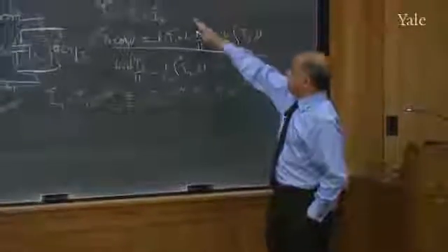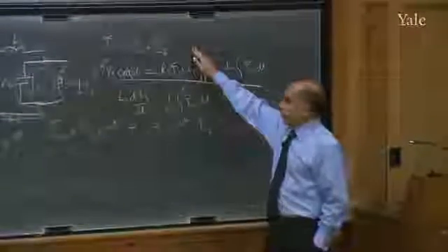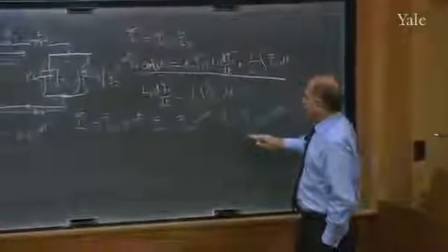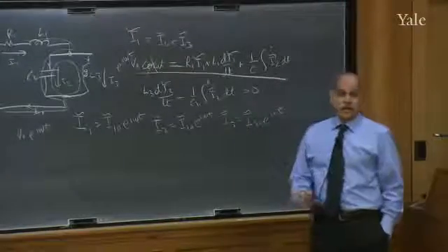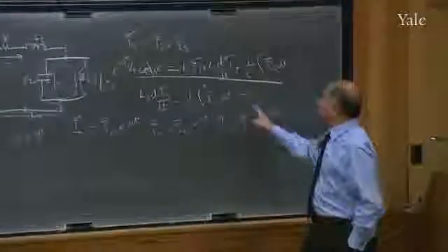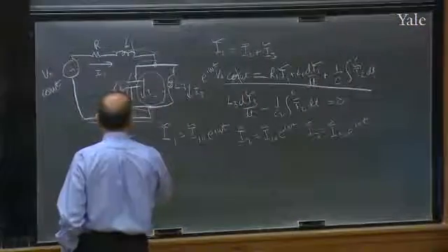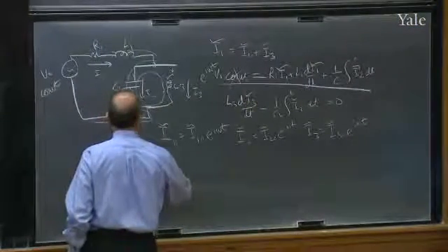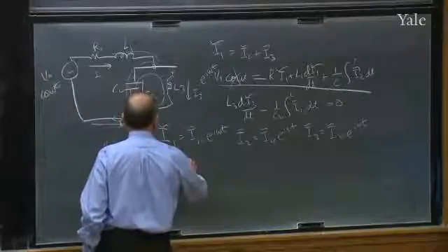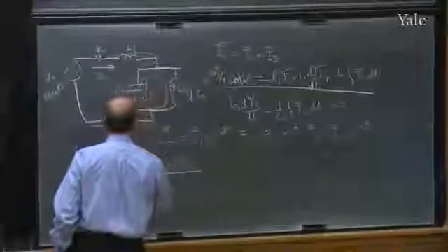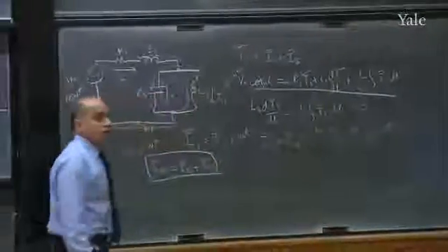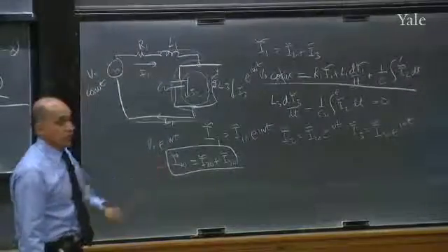And what does this mean? Think about it. Go to the first equation. You equate these twiddle guys, and all the e to the I omega t's cancel on all the three terms. So you get an equation that says I1 twiddle 0 is equal to I2 twiddle 0 plus I3 twiddle 0. No time dependence anywhere. Looks like a DC equation.